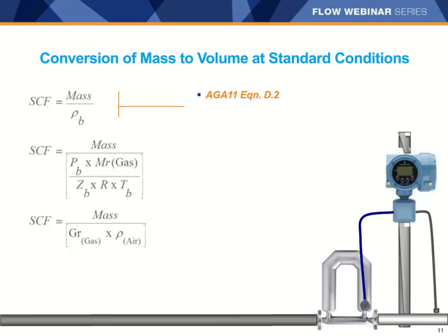The simplest and most accurate path to energy flow units is to multiply the mass flow by the heating value expressed in energy units per unit of mass, and you're left with units of energy flow. However, if you have the need to work with heating values defined in units of energy per unit of standard volume, it is easy to make the conversion from mass to standard volume, as we are about to see, and then multiply by the heating value.